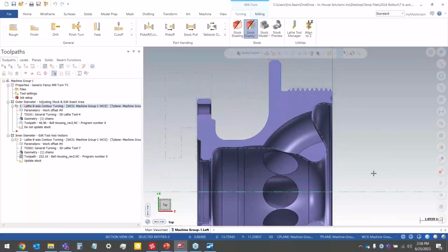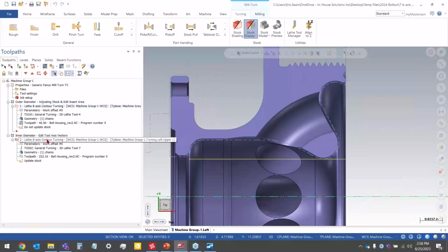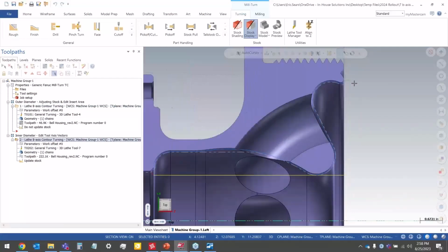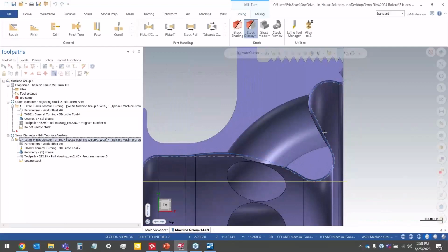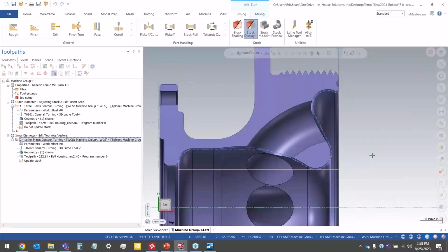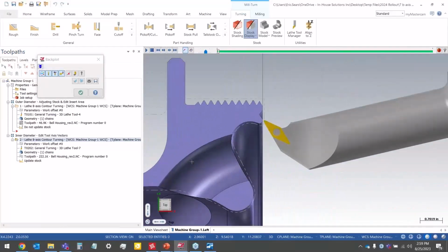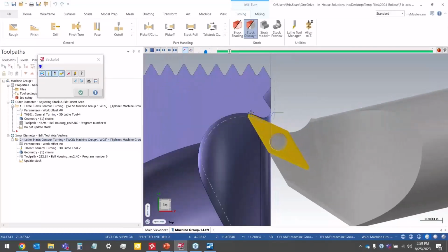The next thing that I want to look at here is machining this inside bore. This obviously produces some unique challenges. Finding a tool that's going to be able to reach all the way along this contour without using a B-axis contour is impossible. So this toolpath, again, is using automatic tool axis control, and we can take a look at what the toolpath was able to come up with. I'm going to backplot this. So here's my boring bar. The lead-in looks nice.